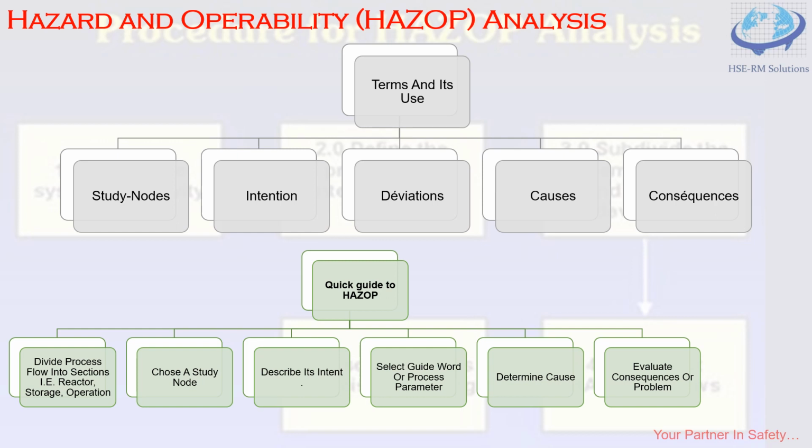As we put the guide word to its use, what are we doing? We are trying to find out what will happen, which gives us our next point, and that is determine cause. So in the third point we defined intent. Then in the fourth point we defined the guide word based on any deviation, and the intended guide word helps us better understand the process defining cause. What will go wrong is described based on qualitative parameter of discussion.